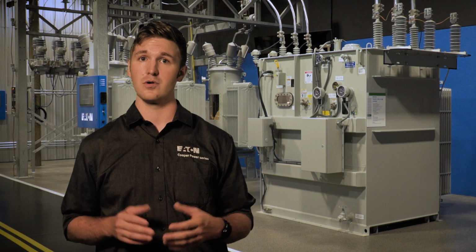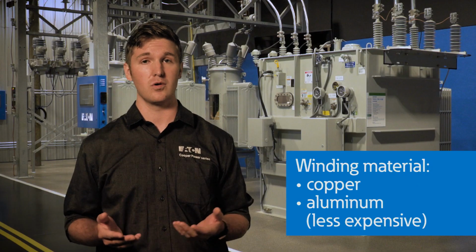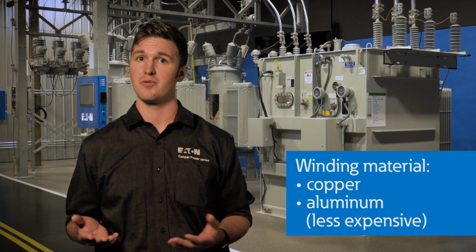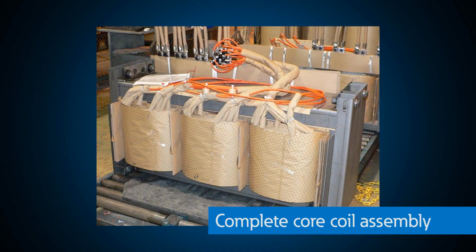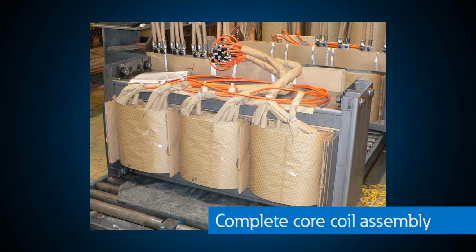Thermally upgraded paper, or in some cases resin, acts as both a mechanical and dielectric barrier for the raw conductor of the windings. The winding material can be copper or aluminum, with aluminum typically being less expensive and offering similar performance on an optimized design. Once the windings are on the core, the coil assembly is complete.